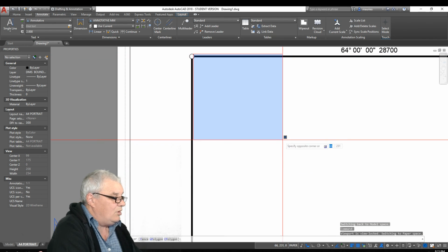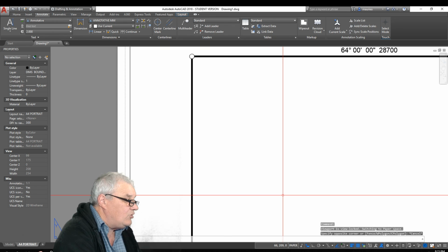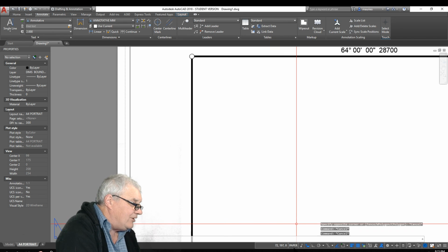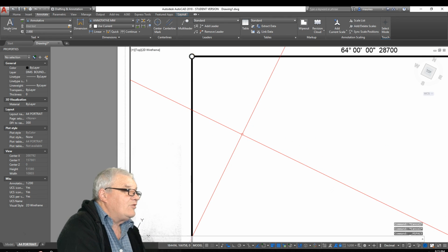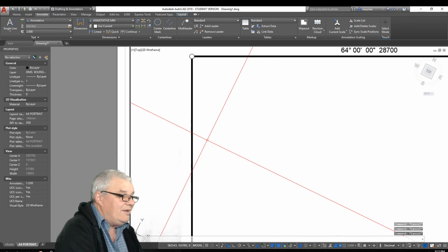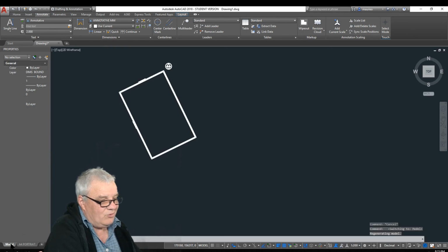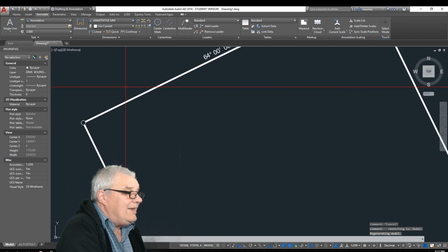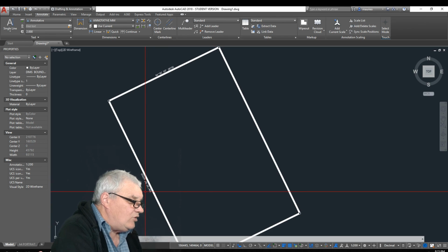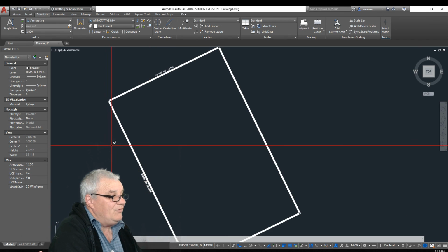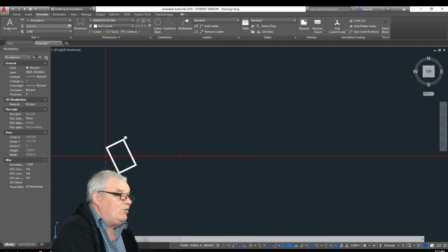Now when you zoom, it does this thing where it goes back to paper space, so we've got to continually make sure we're in model space. So that's all fine there, and of course we could come back to model space here and work over here, but now we have to be a bit careful about the orientation of things in the layout, because we've twisted them around.